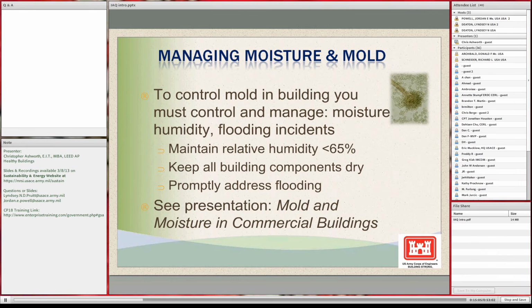So if you have the elevator shafts set up with drywall, but you don't have the building sealed up, which is a very common thing, especially when we're talking about the core of a building. If those do get wet, for whatever reason, having a documented removal of it or management of those moisture issues will prevent issues in the future when the building is completed.